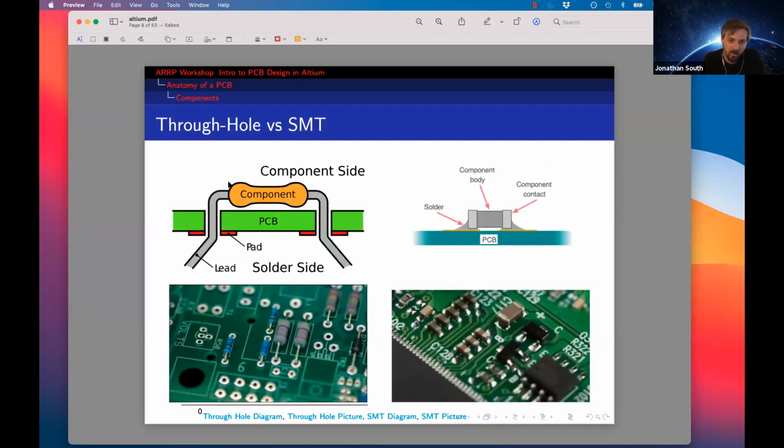And that's what a through-hole component looks like. And you should recognize a lot of those. And here's what a surface mount component looks like, which, they just look like PCBs. Sometimes boards will have combinations of those things. But modern PCBs are all about surface mount components. But sourcing through-hole components and soldering through-hole components is typically a lot easier.